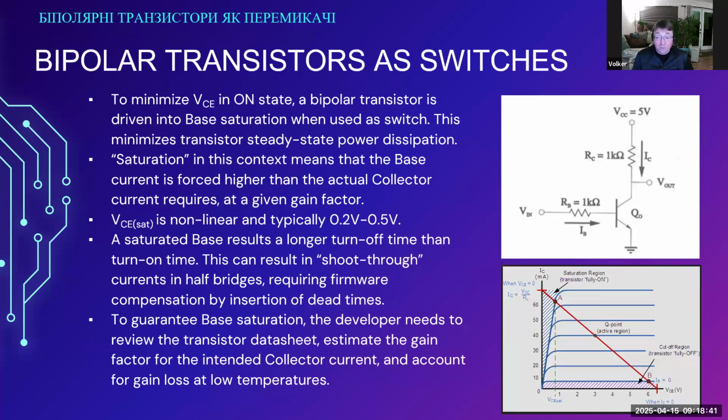And you want to push in a current of, let's say, 5 milliamps. So you take 2.7 volts divided by 5 milliamps. And the resistance value that you get is your new base resistor.